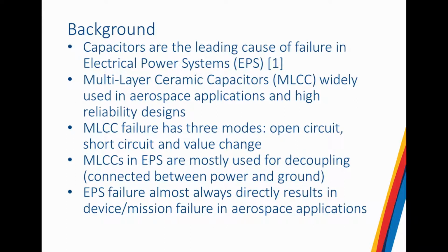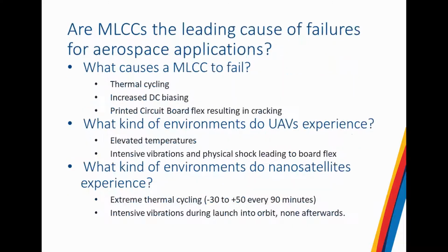Passive devices such as capacitors don't have a high failure rate, so they are not considered in failure analysis, especially in consumer grade type situations. However, for the focus of this project, we're looking at multi-layer ceramic capacitors, especially in aerospace applications and high reliability designs. If the MLCC fails, that could cause electrical power system failure, which could fail the whole system. We wanted to look at the leading causes of failures for aerospace applications.